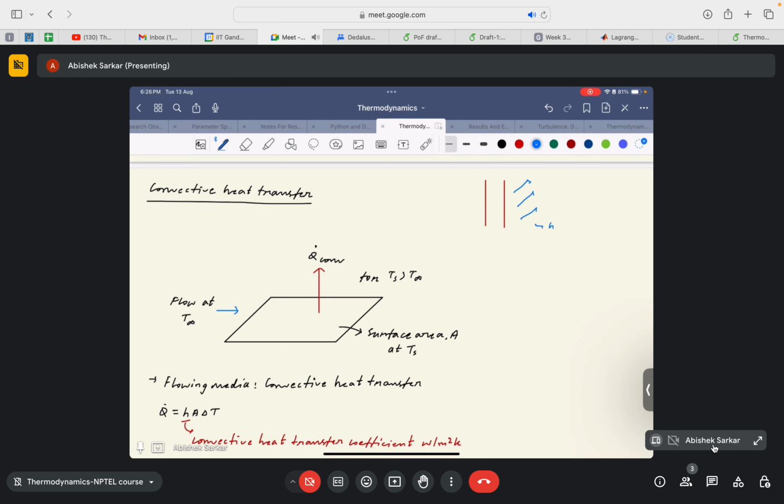Okay, and the room is at temperature T1, the outer surface of the wall is at temperature T2, and the air that flows above the wall along the wall is at a temperature T infinity. Then the net rate of heat transfer because of convection between T2 and T infinity you can find through this formula, right? But the problem is complete when you are able to find the temperature at the inside of the wall, which is T1, right?